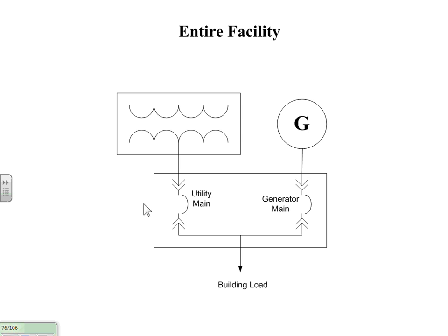Again, the soft load switches, like we discussed before. Utility goes out here. First thing the controls in this gear does is open this utility main. A little bit of a review here. Generator set starts, comes up to speed and frequency, closes the breaker, doesn't care because the utility's gone. It just shuts the breaker when it's ready, and it provides power back to the building. Utility power comes back, transformer heats, this breaker is still open.